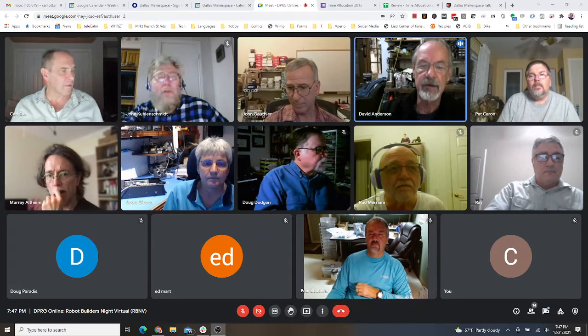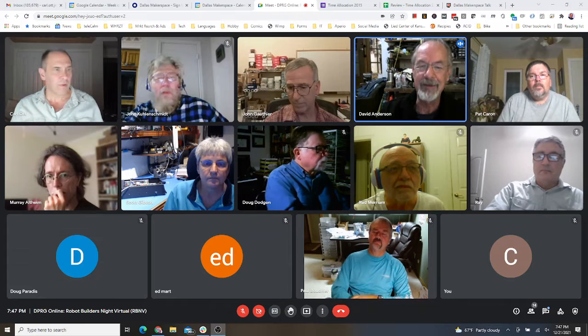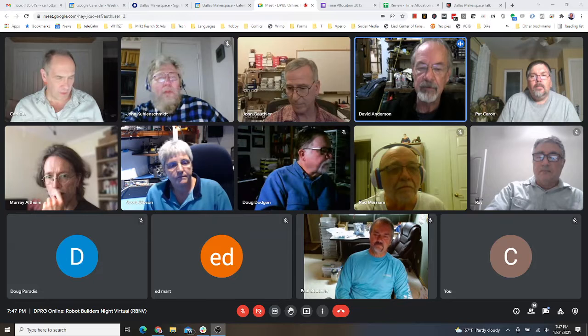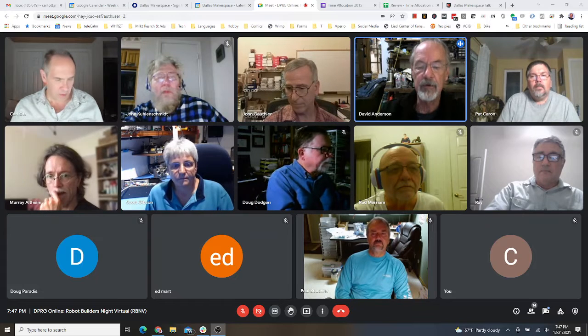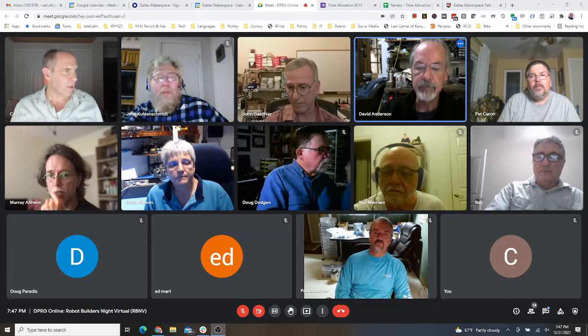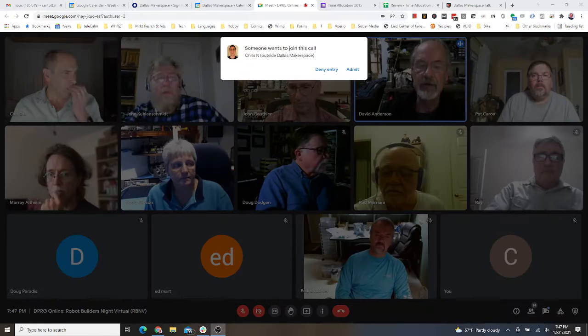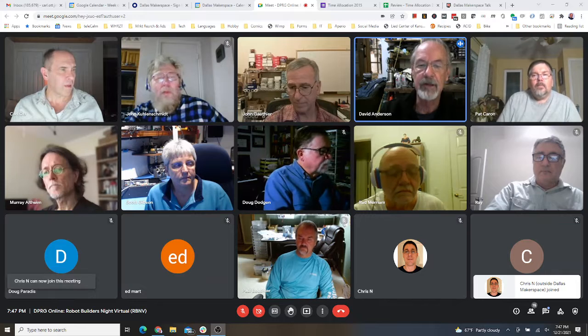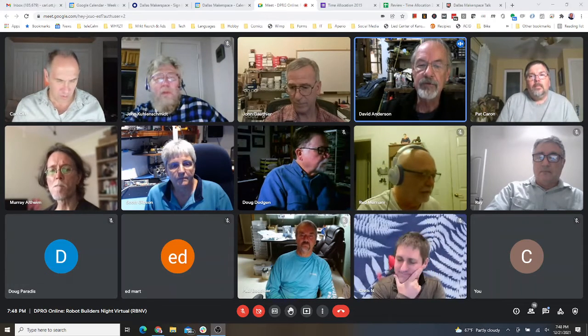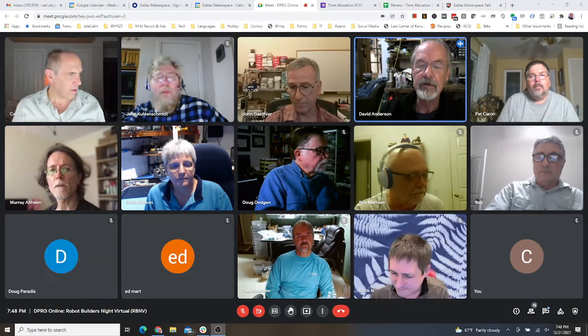Now, another way you can get that same angle, remember we're sampling this at a certain rate. So let's say we're doing it at 100 hertz, just to make the math easy. At that rate, you're calculating how much the robot has turned during that previous 10 milliseconds. And so you could also have a rate gyro, which basically gives you rotations in degrees per second or something like that.